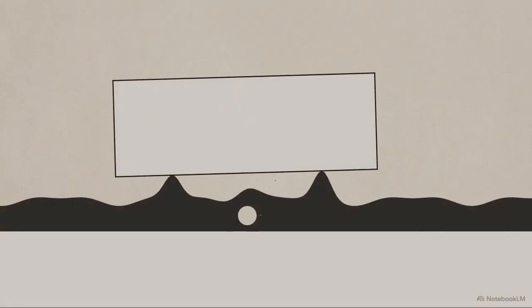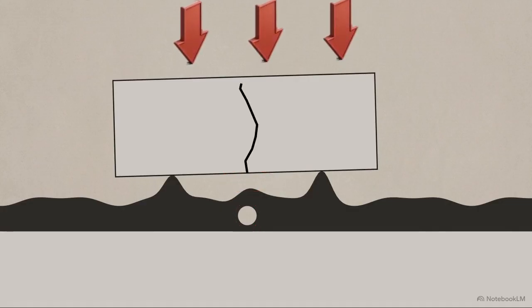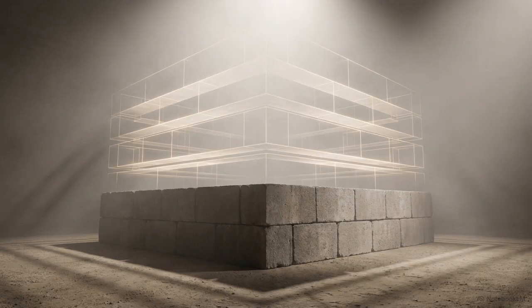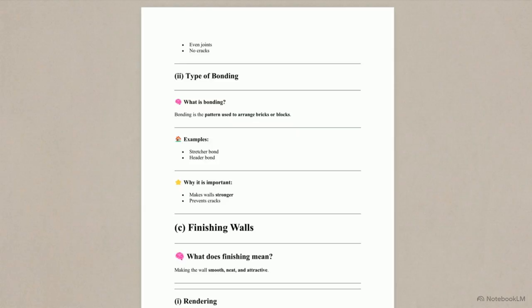If the mortar is spread unevenly beneath those first blocks, it creates tiny air pockets and pressure points. Under thousands of pounds of downward force, those uneven weak points can cause the bricks to crack. That first row of blocks must be perfect. It acts as the geometric blueprint, setting the exact level and alignment for every single layer that will be built on top of it.